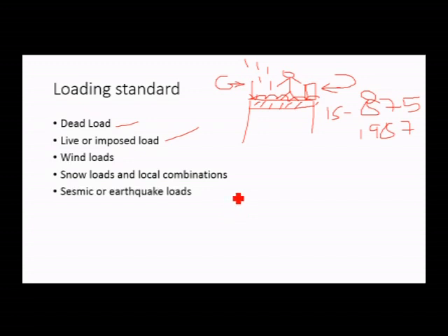And wind load should also be considered. The wind load which is acting on the structure depends upon the location of structure in India and is specified in the same IS 875 1987 part 3. And for multi-story structures, water tanks, towers, chimneys and other types of tall structure, wind load should be considered in design. Wind load acting on structure is influenced by the plan, dimension, height of structure. Location of the design wind pressure is specified in the Indian Standard Code.